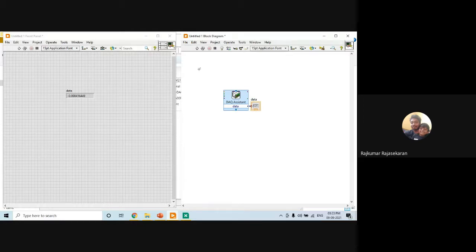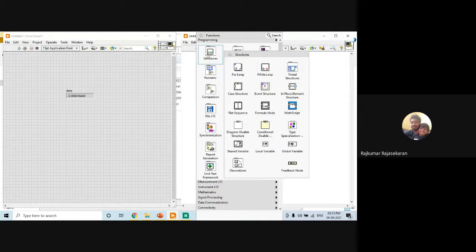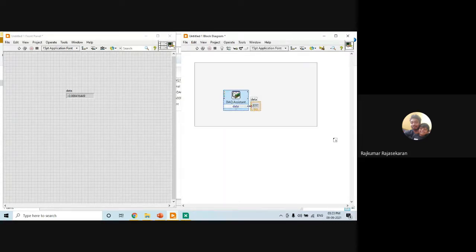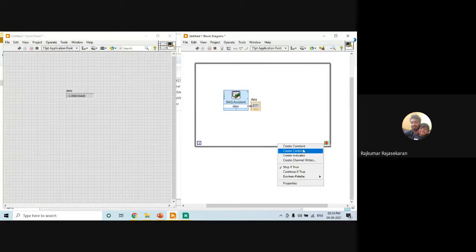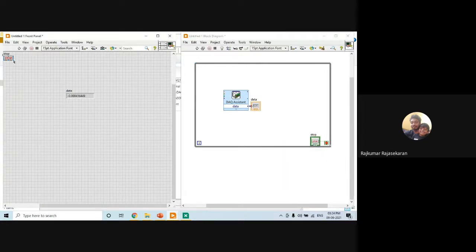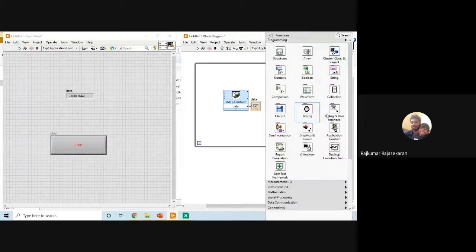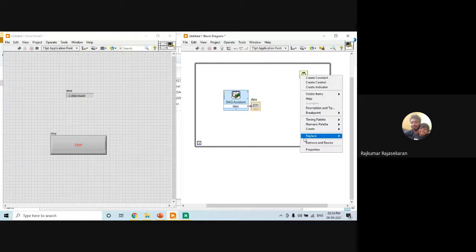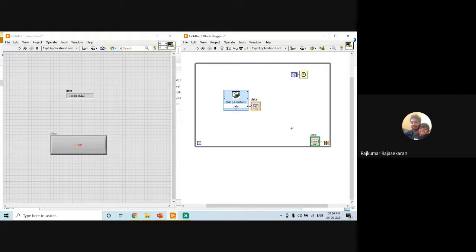Right now we are just going to make measurements one by one; every time we click, it's going to make a measurement. But of course, if you know how to use LabVIEW effectively, you can make use of some programming constructs and make the measurement continuous. You can also include a stop button to stop measuring, and you can also add some sort of delay. Instead of making measurements as fast as possible, you can make the measurements timed, like every 250 milliseconds or something.